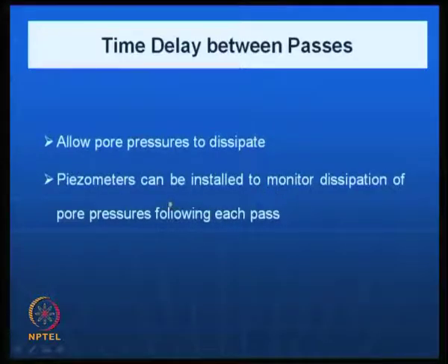In the case of clays, you can put piezometers. Piezometers measure pore pressures and help you monitor the dissipation of pore pressures in each pass. One can do a lot of experimentation there, trial and error. This is going to be very effective. In the next class I will show you some video of how this process, dynamic compaction, could be done, and some case studies.